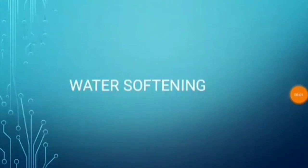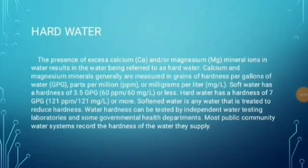Water softening. Hard water. The presence of excess calcium or magnesium mineral ions in water results in the water being referred to as hard water. Calcium and magnesium minerals generally are measured in grains of hardness per gallon of water, parts per million, and milligrams per liter. Soft water has a hardness of 3.5 GPG or less. Hard water has a hardness of 7 GPG or more.